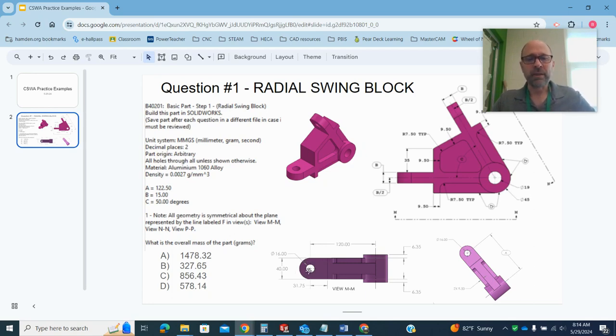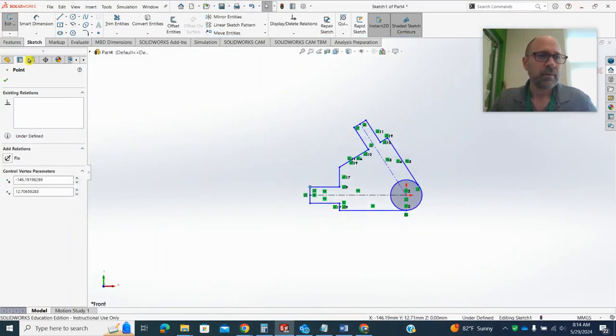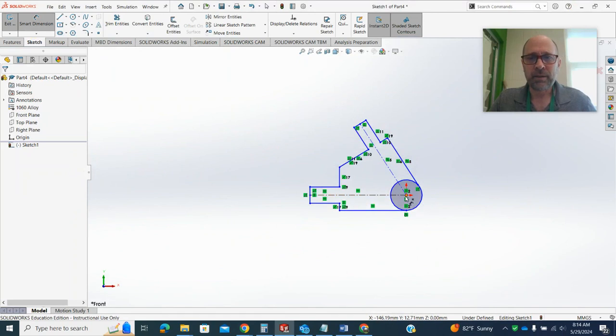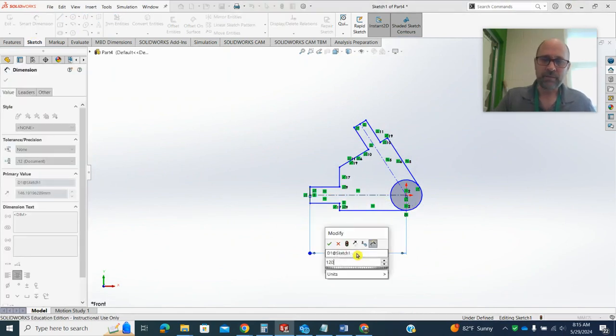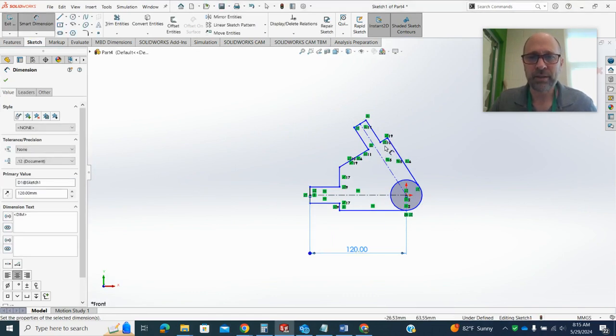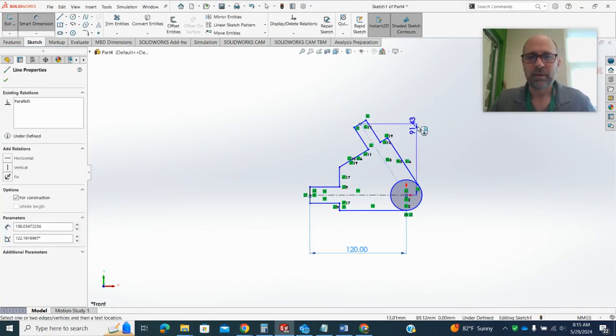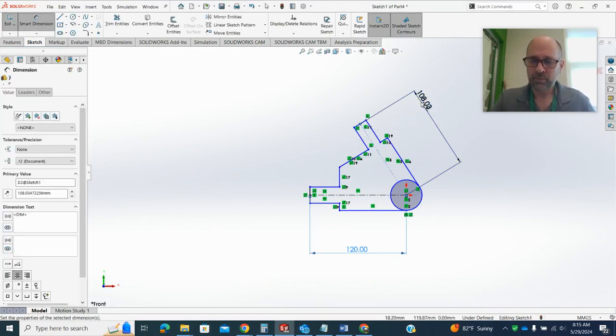or I can leave it be and just create another extrusion. I think I'll do that. I'll just make it 120, and then the second one I'll make whatever A is, 122.5. Then I'll add material and create a hole. All right. I like to make the models match the dimensions provided because it makes it much easier to check things. I think I said this is 122.5.